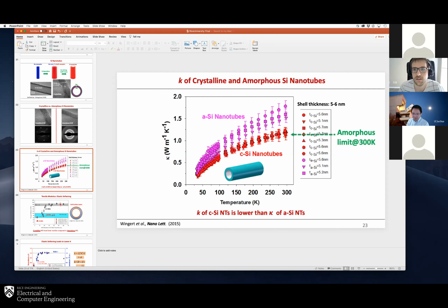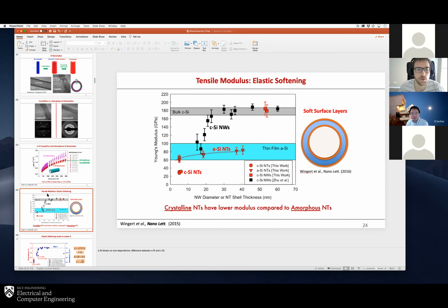Thank you. I have two questions. The first is regarding this particular work about the silicon nanowires. It's very interesting that the Young's modulus drops significantly in both shells. Do you consider which acoustic mode contributes most to the reduction of the thermal conductivity, or is there no distinction? The reason I'm asking is that it is possible to independently check by optical means whether the Young's modulus or the sound velocity changes, and compare that with the thermal transport measurement, which also includes the contribution from the scattering rate. That's a great question. The short answer is we don't know. We have not really studied that in detail.